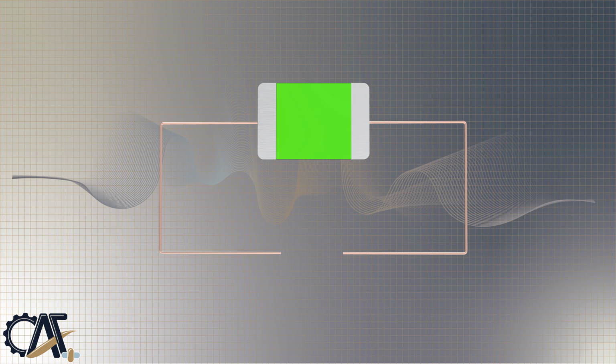To do so, let's connect the conductive plates to a copper wire and use a DC power source, in this example an AA battery, to complete the circuit. As soon as power is applied, current starts flowing and the capacitor charges up. This means the plate on the capacitor that attaches to the negative conductive plate of the battery accepts electrons that the battery is producing, and the plate on the capacitor that attaches to the positive conductive plate of the battery loses electrons to the battery.